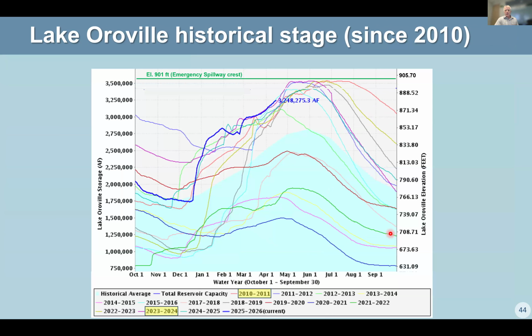This is just a picture of, while we're talking about reservoir elevations, I have 16 years of reservoir data. The reservoir elevation has been measured every day since 1979. So you can see that it's not unusual for the water to get up to the emergency spillway. In a good year, it's there, and then it's operated to stay there. When we have dry years, it's down here. It's not unusual for it to be a lot lower. What is unusual is for it to be average.